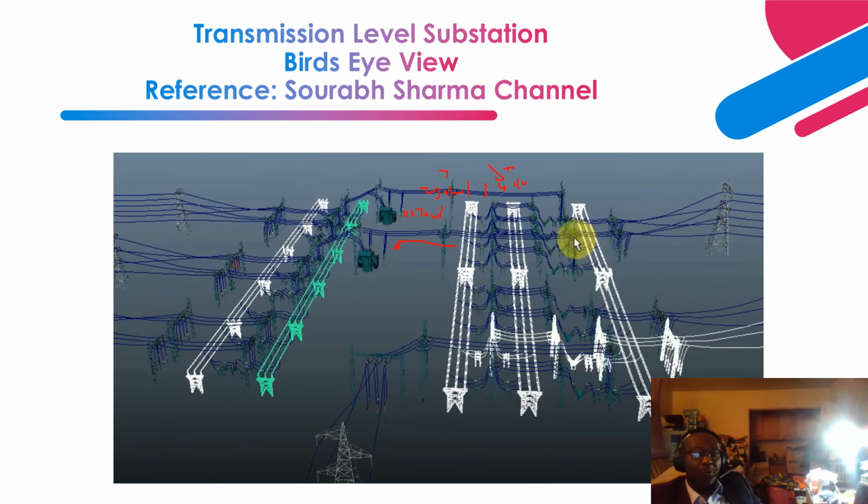And we've been fortunate enough to also leverage this transmission level substation in close proximity to the transmission level voltage. So it goes through a step-down transformer, which steps it down to, let's say, 69 kV, 34.5 kV, different levels of voltages. If it is 765, then I can go to 230 kV or 115 kV, to send it out to another substation.